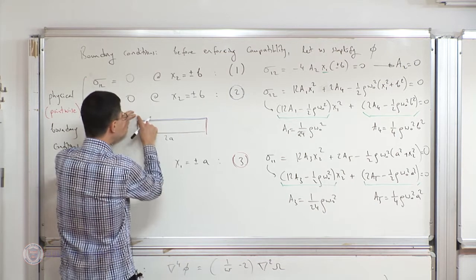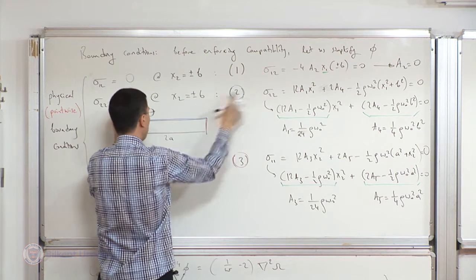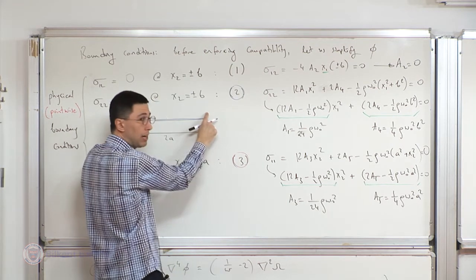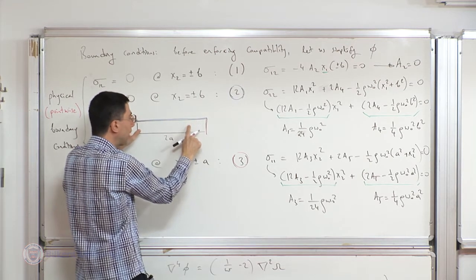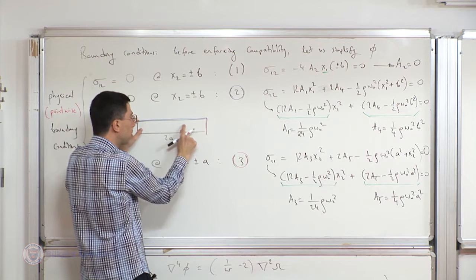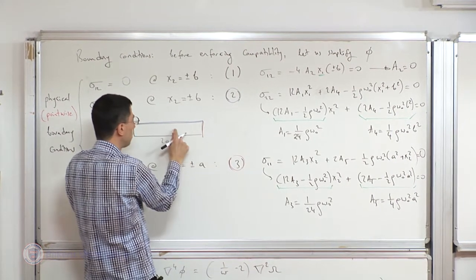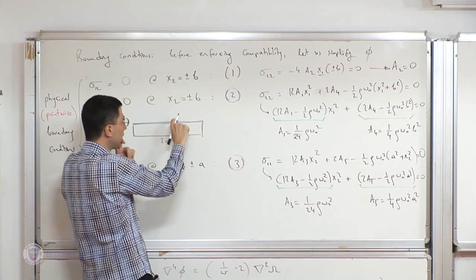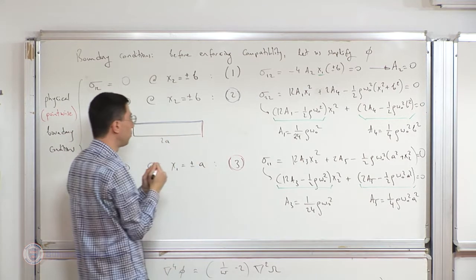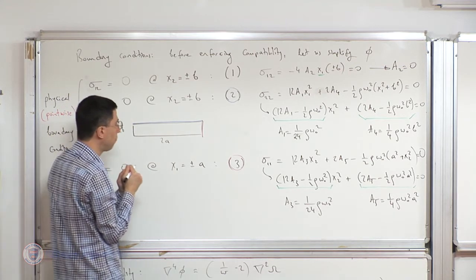So I don't want to sacrifice from this condition on sigma 2 along this very long edge, because if I sacrifice, any error will quickly penetrate very deep into the structure and affect the stresses even already here, which is going to be something perhaps considerable, looking at the thickness of this beam. Again, maybe it's not very intuitive, but very soon with a COMSOL numerical example, we're going to see that influence.